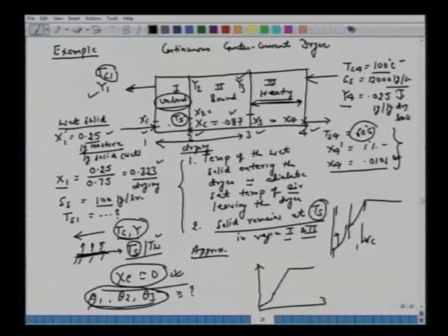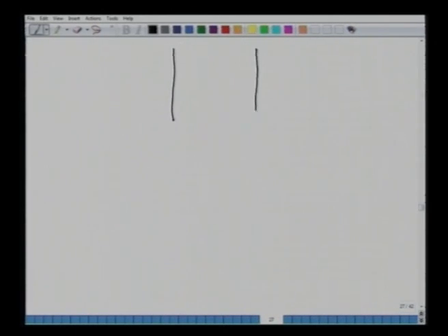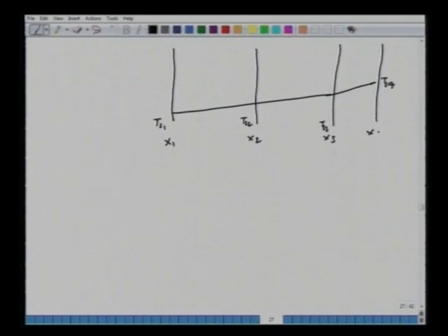All right. So for a problem like this, if you recall from our previous lectures' discussion of the analytical solutions and analytical expressions, one has to identify the humidities and the solid moisture content. So before that, let's draw another schematic for our calculation purposes. Now we have 3 regions. Solid temperature increases like this, as you would expect. So we have Ts1 entering, Ts2, Ts3, then it further increases to Ts4. Moisture content X1, X2, X3, X4.